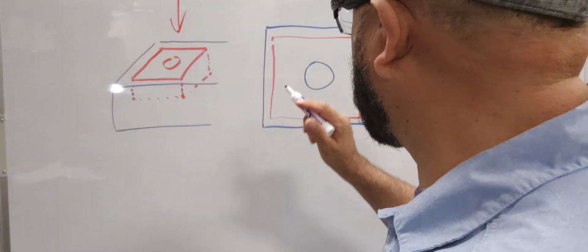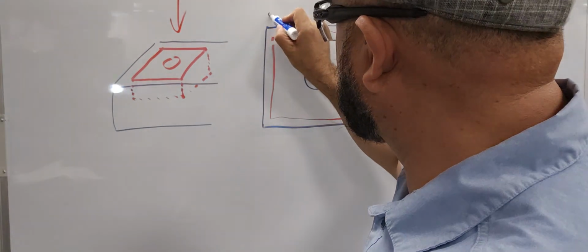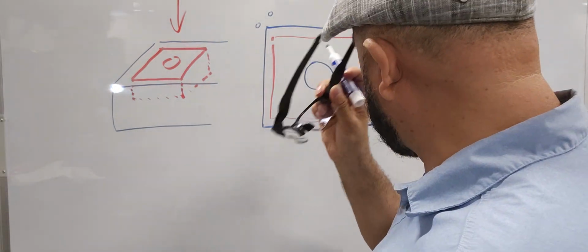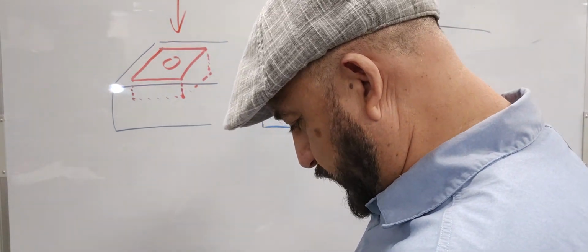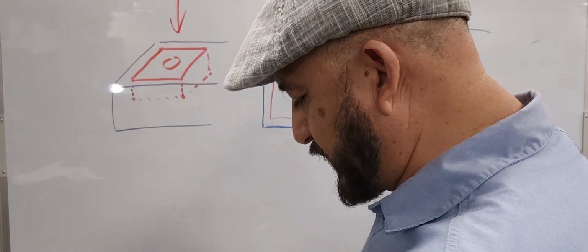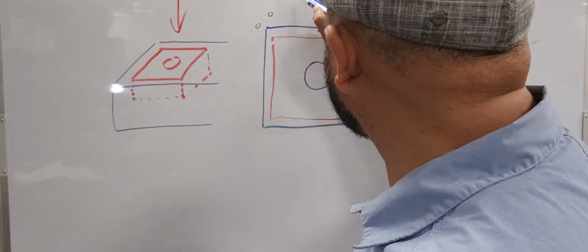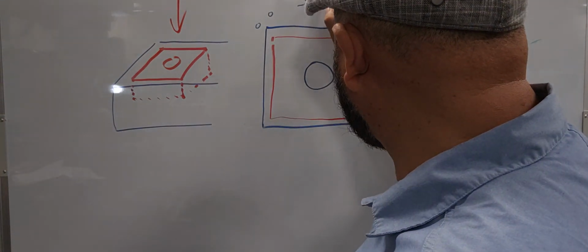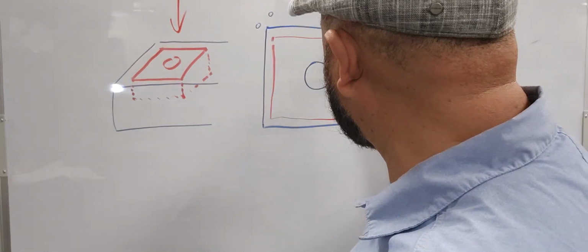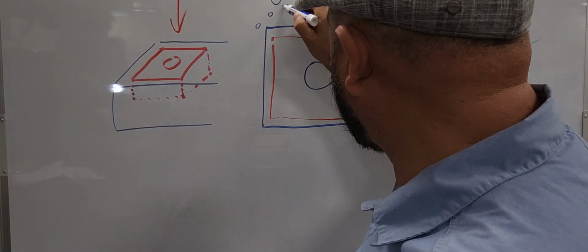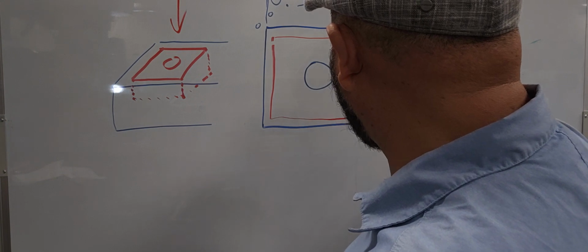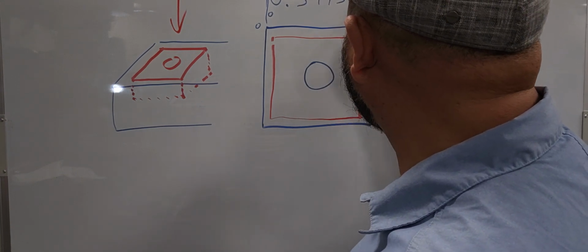If we start here as this being the 0, 0, x and y, then the center of this, well, actually we have to go from there to the edge is 347 thousandths of an inch. So 347. It's 5/10, but don't worry about that much. 0 point, so from this edge all the way to this edge right here, the edge that defines that is that long.